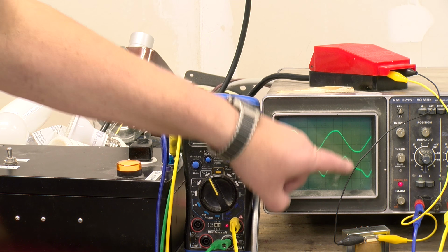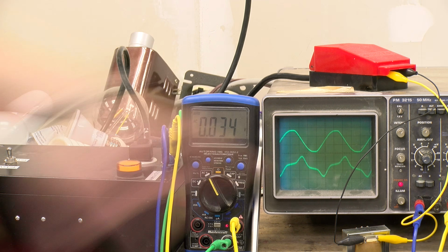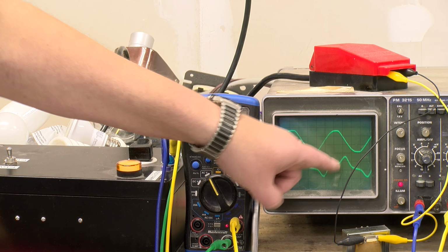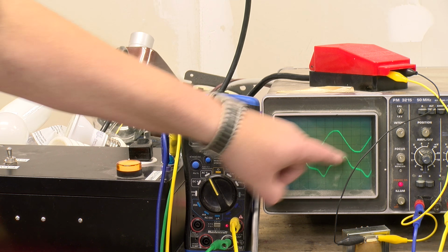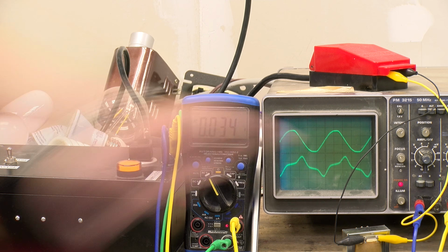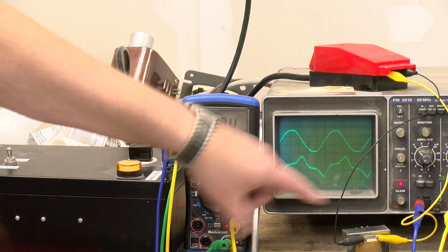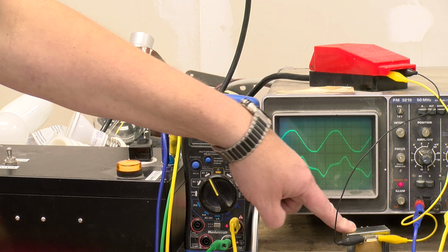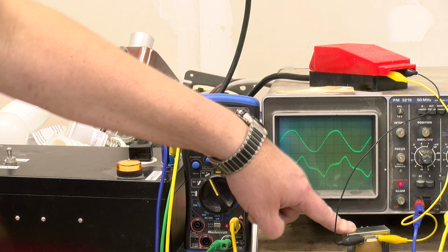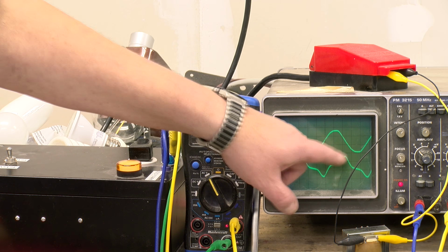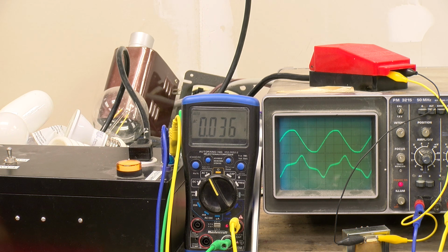And once again, we see that same characteristic of a magnetic core beginning to get up to the top of the saturation curve at the peak of the current. And just as I said about the other one, if this thing was under full load, we would probably have 10 times the current flowing in this peak, and so you'd hardly notice it at all.